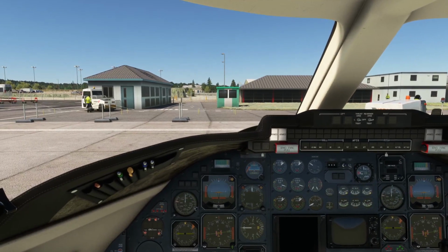There is another form of protection as well, which is a series of current limiters, which act as a form of slow trigger fuse, and they are in the tail cone. They're not something that pilots can access in flight, and if a current limiter blows, it has to be serviced on the ground. And the purpose of the current limiters is to prevent a cascading electrical failure occurring.